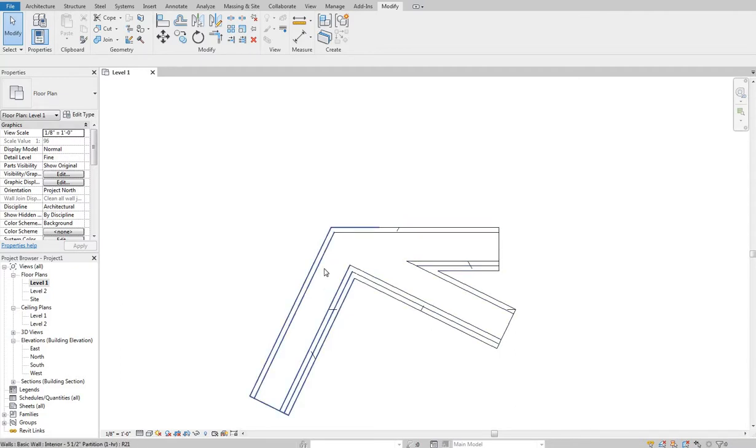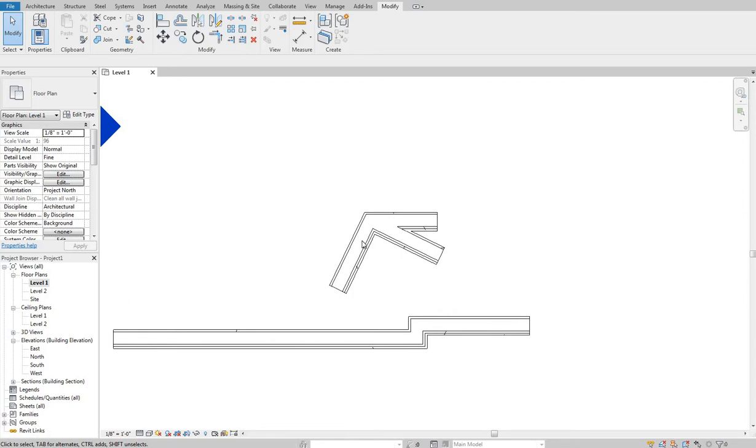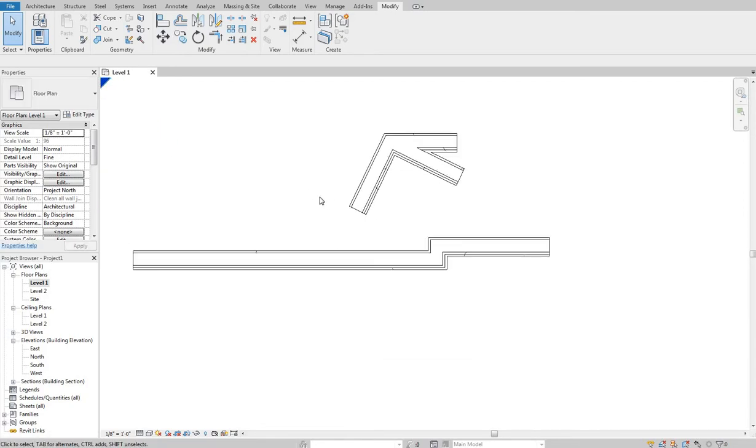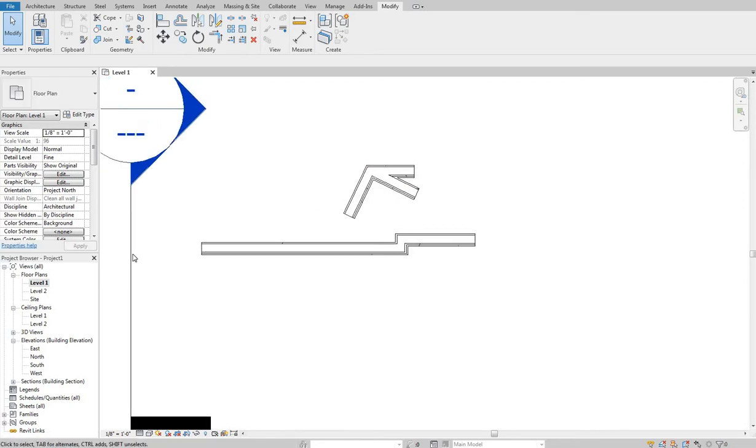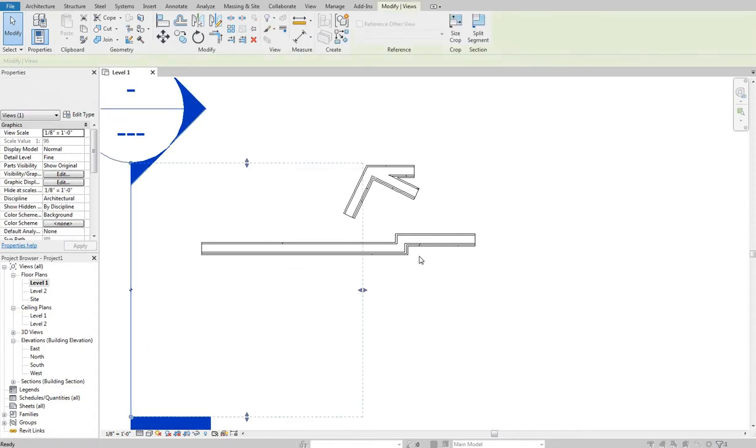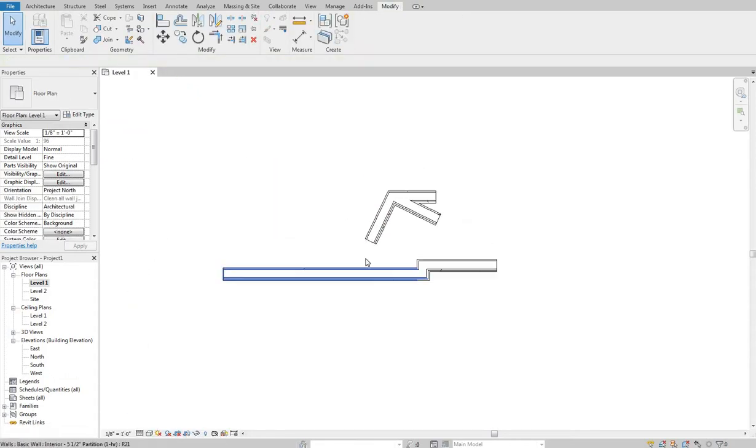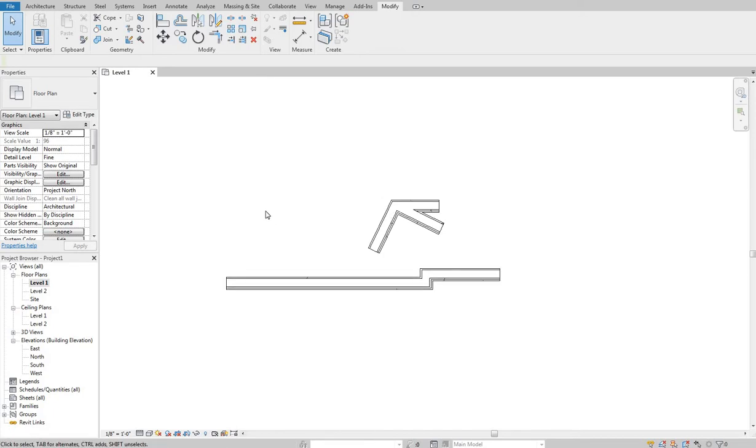So this one's actually going to stick into the window. If you come in with wall joints and just miter it at the corner, that'll eliminate the problem and you should be fine. So that's a brief rundown of wall joints, of stacked walls and how I like to use them, and then just how edit profile and things like that work.